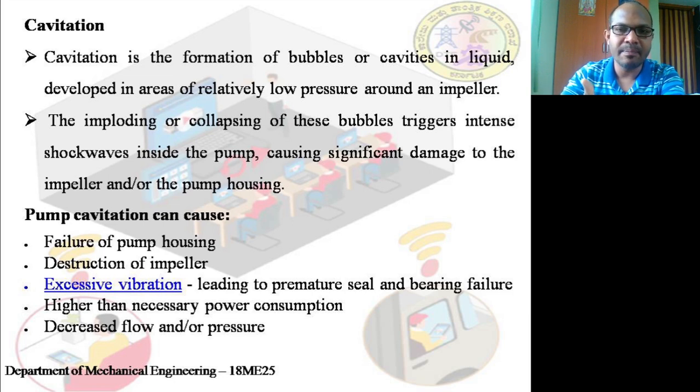So in case of leakages or failure of any sealing material, or failure of the foot valve or the strainer, what happens? Air may come into the passage of the suction valve or into the suction pipe.